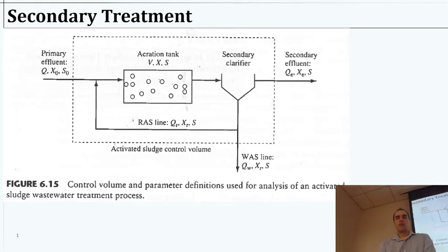So, for our aeration basin, really what we want to know is how many bacteria are there, how quickly are they consuming the food, and what impact does it have on their food, which is the waste that we're trying to treat. So that's sort of the concept, and then we want to collect any bacteria that we just produced with this process and capture them before those bacteria discharge into the rivers, waters, wherever we're sending it, because we don't want to contaminate the outgoing water.